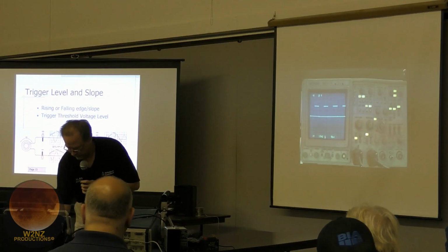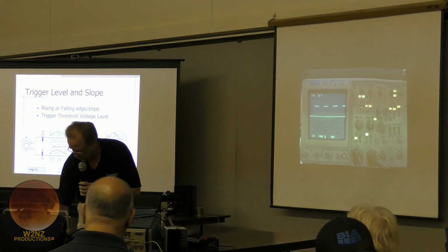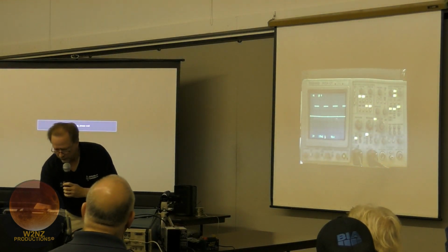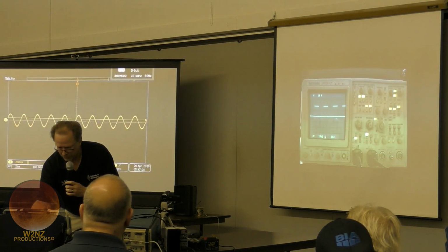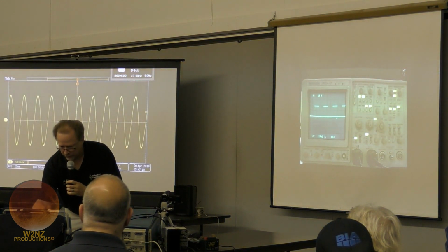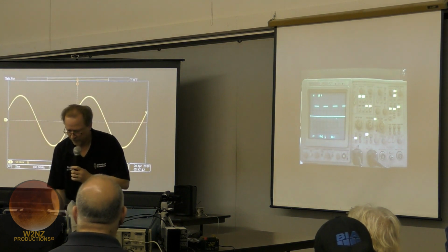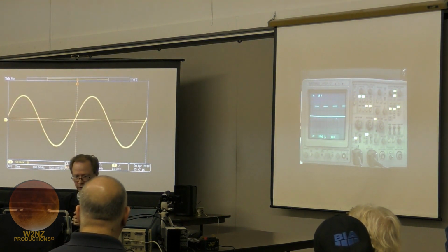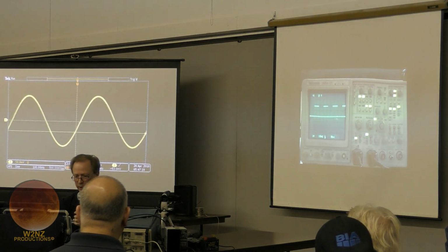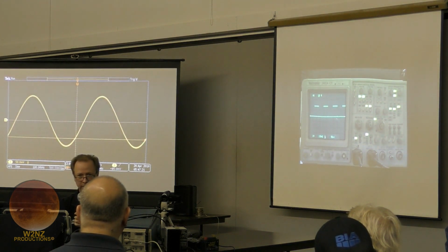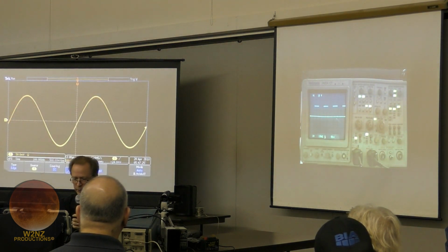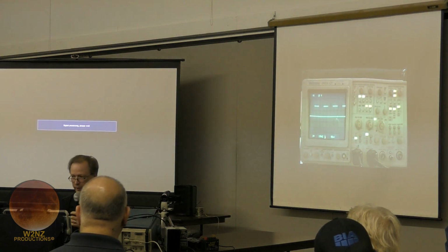Let's take this signal here. I'm going to put this scope up on the display here. This is something easy for me to show you. Let's bring our trigger level down. Okay, so we can actually see I've got just a sine wave here, right? If I adjust my trigger level, you can see that it actually draws a level on there. As I adjust that level, where that trace is starting is where I'm crossing that. And in my trigger menu here, I'm triggering on the rising edge.